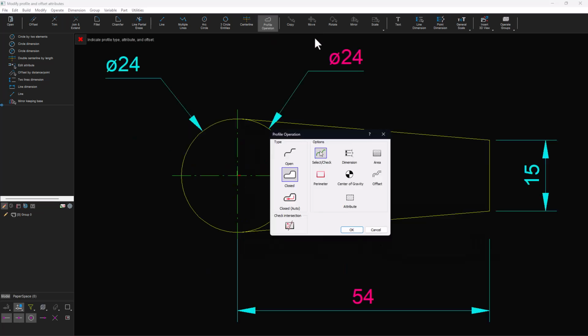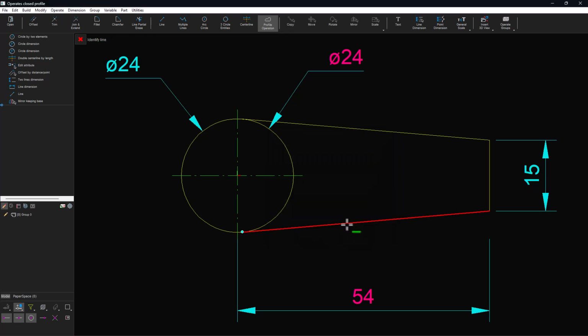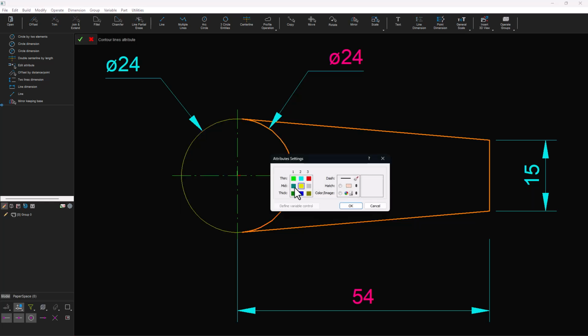Creating a fill area on the right side. Open the Contour command. Set Closed Contour function, Attribute option Edit, and Intersection check. The function will check all the lines that intersect the contour, and not only at the ends. Indicate pattern with type and hatching with a distance.